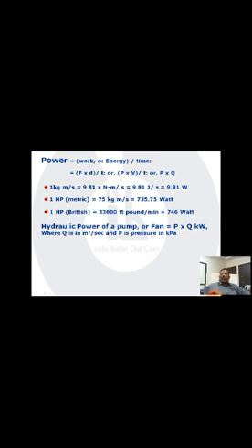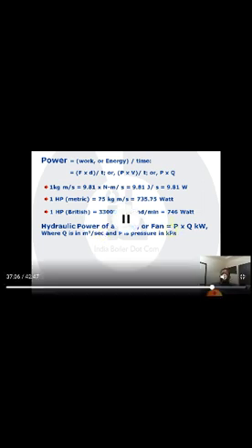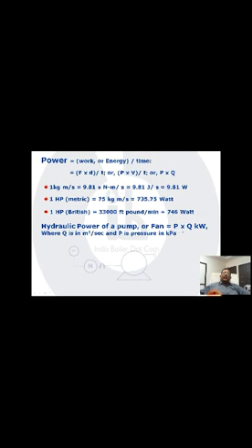Okay, that's why I told you that the kilopascal is the most useful pressure unit so far as BOE calculations are concerned. So the volumetric discharge will be in meter cube per second, the pressure will be in kilopascal, right? Now let us say I talk about the pump, which is being powered by a motor. The shaft is moved by a motor, and the motor is getting power from the source. Now there is the source power, the motor output, and the pump output or fan output. This output of the pump or fan is known as hydraulic power.